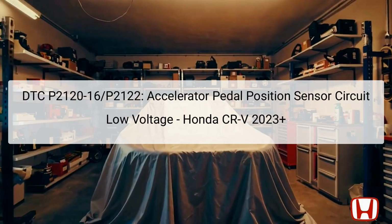The Diagnostic Trouble Code (DTC) P2120-16 arises when there is an issue with the Accelerator Pedal Position (APP) Sensor A or the Throttle Position (TP) Sensor D circuit. The APP sensor is integral to the accelerator pedal module, which translates the position of the accelerator pedal into a corresponding voltage signal. This signal is received by the powertrain control module, PCM, which uses it to adjust engine power and performance accordingly.